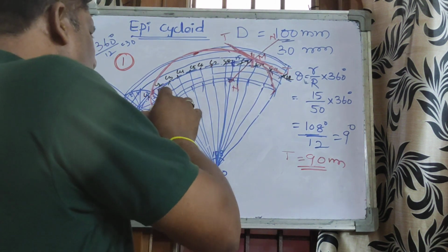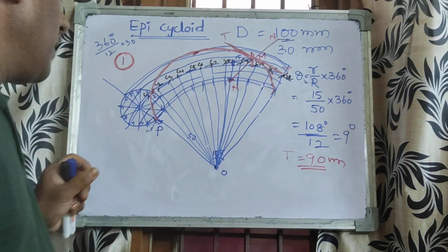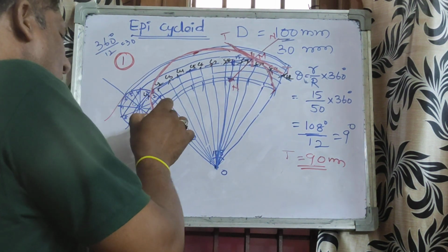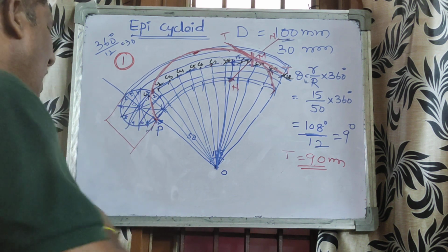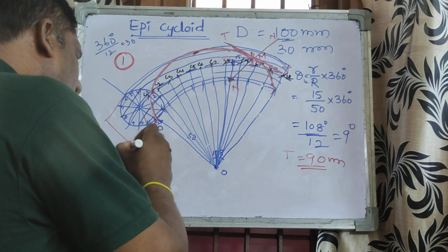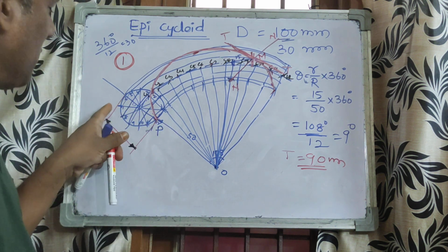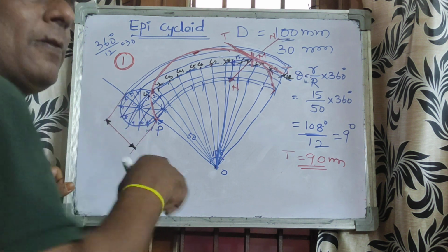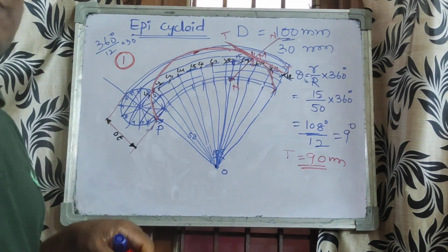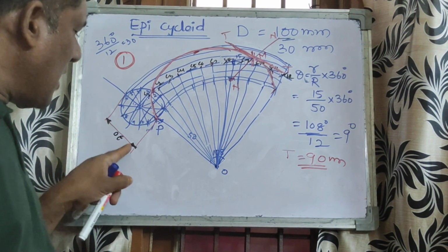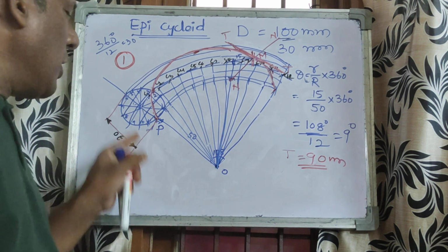Suppose here the actual solution is curve, tangent and normal. These three are with HB pencil. Afterwards, go for dimensioning. Dimensioning is also very important. So here the dimensioning arrow marks are with HB pencil. Whatever extension lines are there, all with 2H pencil. Suppose this diameter is 30 mm, like that you have to write 30 mm. So numbering with HB and this arrow with HB, remaining extended lines, border lines with the 2H pencil.